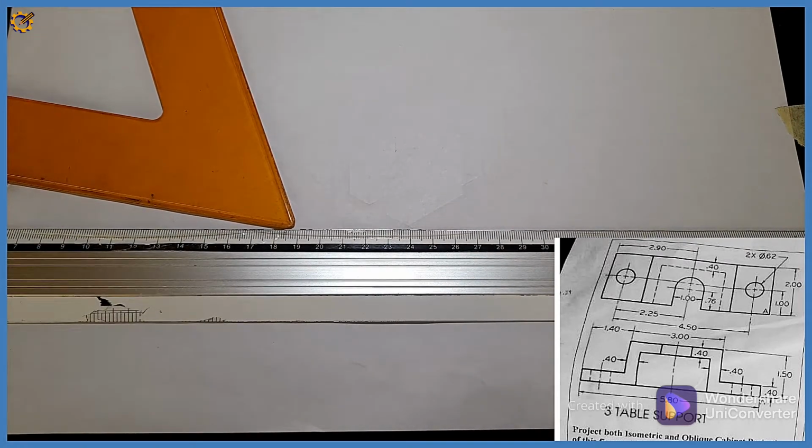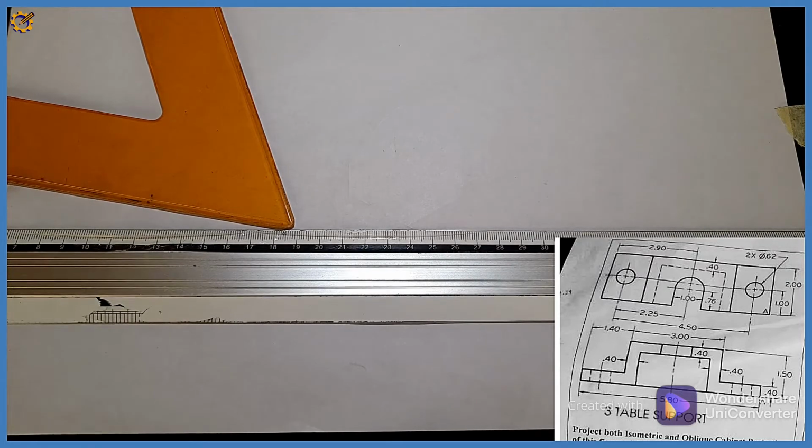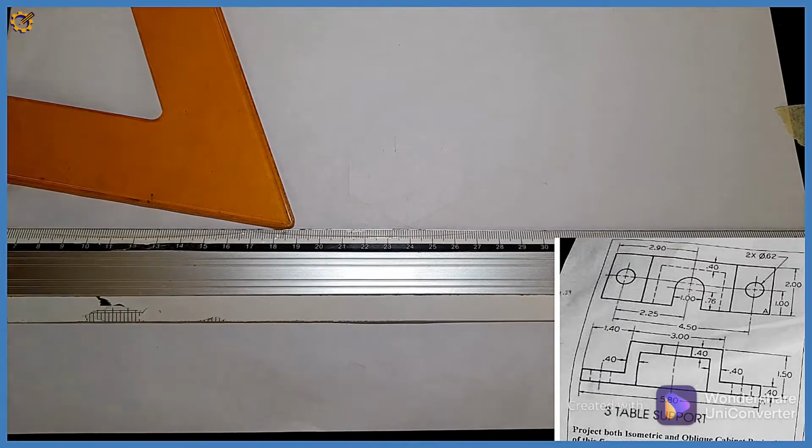Alright, so for today we'll be looking at a problem on the screen which is given in third angle orthographic projection. We have the plan at the top and the front view underneath. We'll be reproducing this object as an isometric drawing, which is a three-dimensional view. To do this we are going to convert each of those dimensions to millimeters, and we are increasing the scale by 2, which means along the way we are going to approximate some areas.